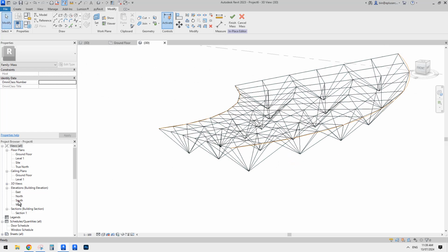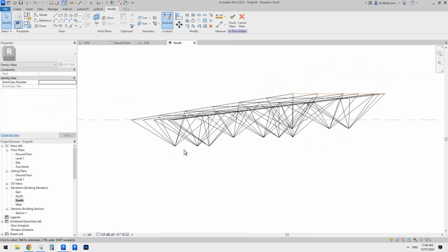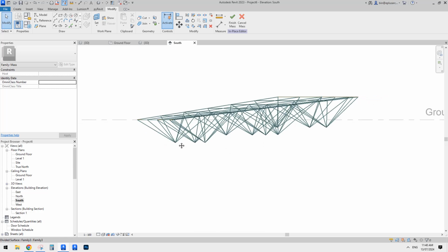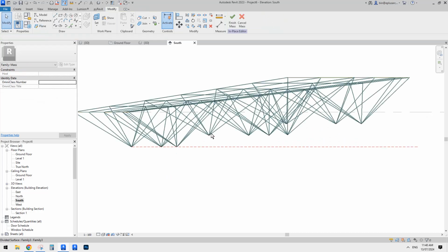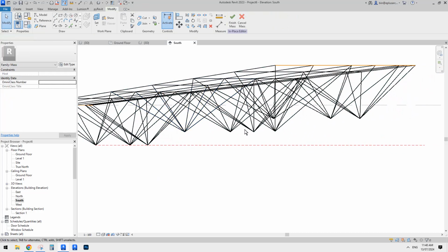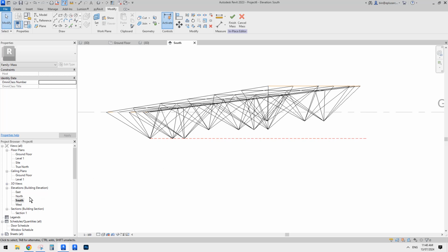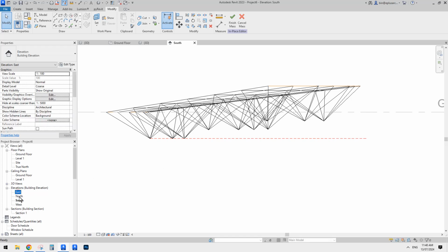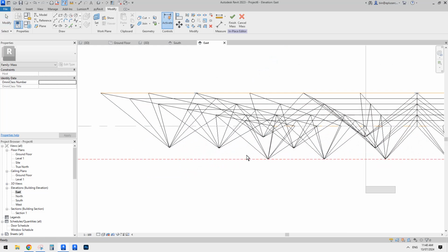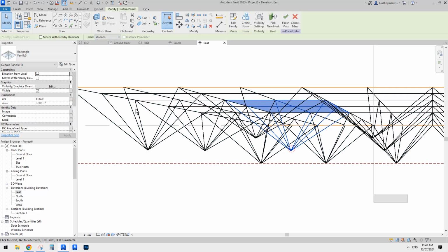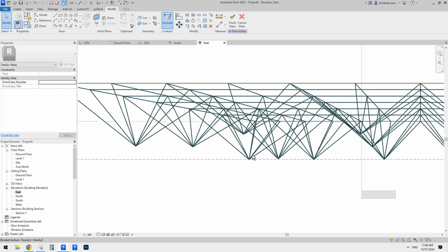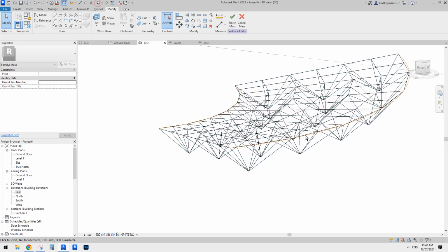So now this means if you go to elevation and try to have a wall underneath, I can just roughly draw a reference plane. It's a bit hard to see from this elevation, so let's try east. Yeah, that's better. So for example, this one's okay, this one needs to come down a little bit, maybe 1300, maybe more, 1500, yeah, something like that. And let's go to 3D view.